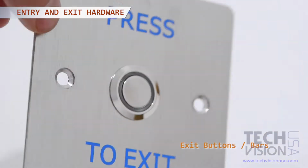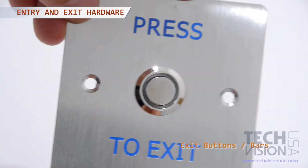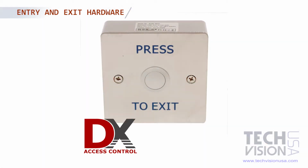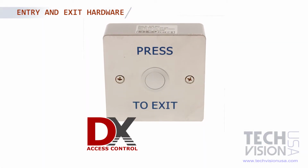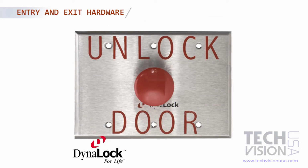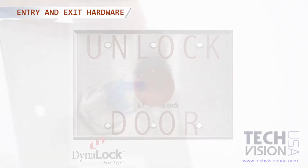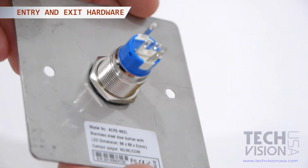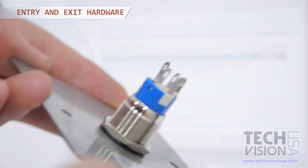Magnetic locks. Maglocks are electric powered magnets that will hold the door closed until the system sends a signal to unlock the door. Exit buttons and bars usually go on the other side of a door and allow a user to request to exit from a secured area. There are a variety of exit buttons and bars. Some are simple electric-powered buttons, and some are pneumatic. Pneumatic buttons do not rely on power, so an exit is possible even when power isn't available. There are also exit buttons with a delay for more secure areas, where the user must wait a few seconds before an exit is possible.